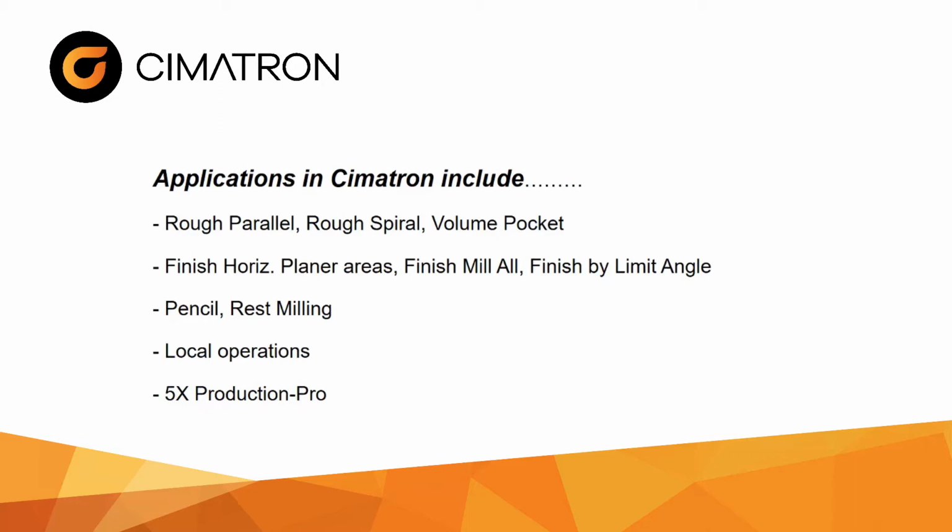Most of the time when using these types of cutters, what can be tempting is to try and use it for every situation. Traditionally, we put in a bull nose and we just start cutting everything. This type of tooling is specific to the surfacing you are working with, so each tool has an ideal angle range that it works in. We wouldn't want to load one tool, let's say a barrel cutter, and then try and finish a whole core with it, unless that surfacing was ideal for that type of tool.